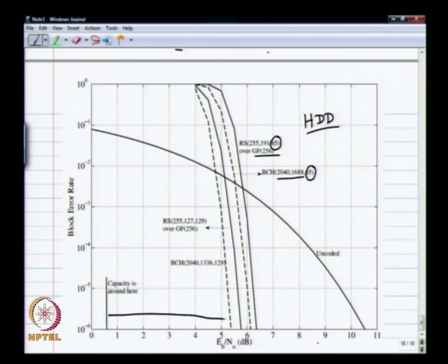So that's something that's valuable, right? Hard decision decoders are much simpler to implement. The PGZ decoder is not too complicated. Its complexity is not exponential in K, right? It only depends on the error correcting capability. So it can be implemented, and you get decent coding gain. But the only drawback of these codes definitely is this gap.